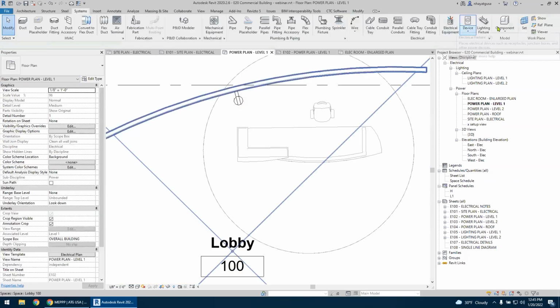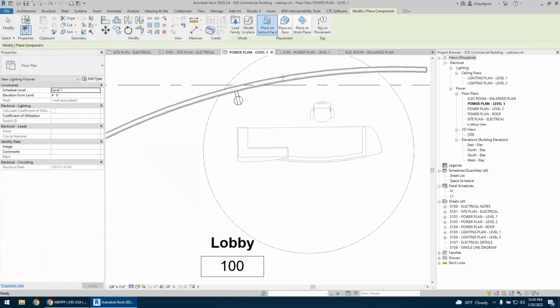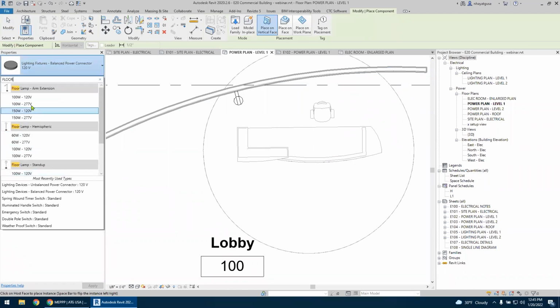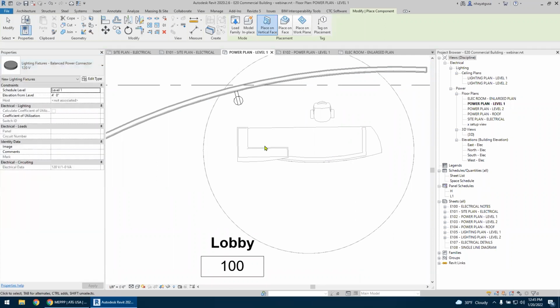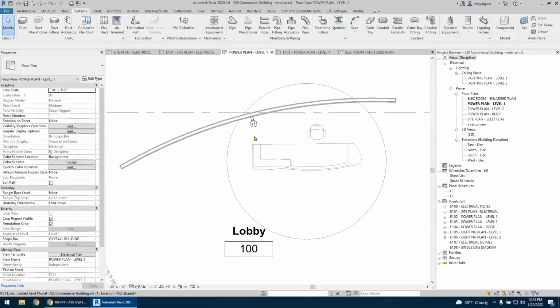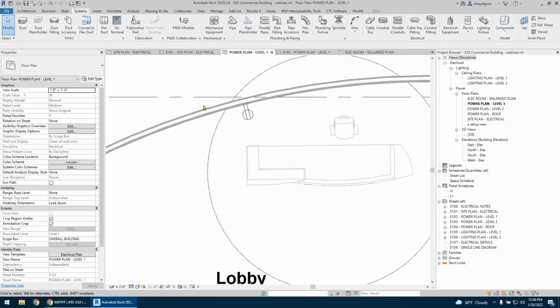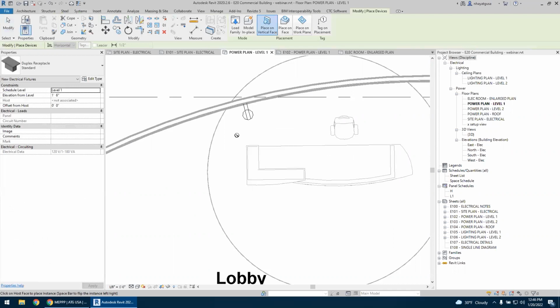If you're looking for anything and you don't know what it's categorized as, you can click component. That's like everything in Revit. So I click the drop down, I'm typing floor lamps. That's all they give us, floor lamps, no floor receptacles. The way I got that on that floor again, it's trying to stick to the wall, but let's go back to that. Systems, device, fixture.